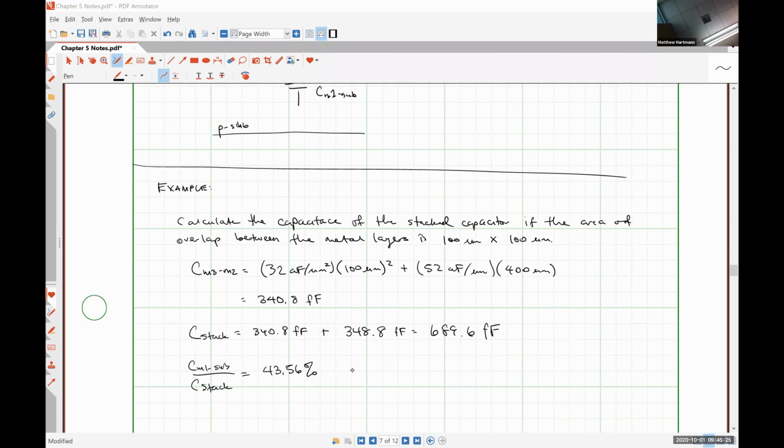So you may wind up making a metal to metal capacitor as what's called a compensation capacitor, which will help with phase drift in your op amp. Anyway, this is a way to do that without adding too much parasitic capacitance and also minimizing the footprint.